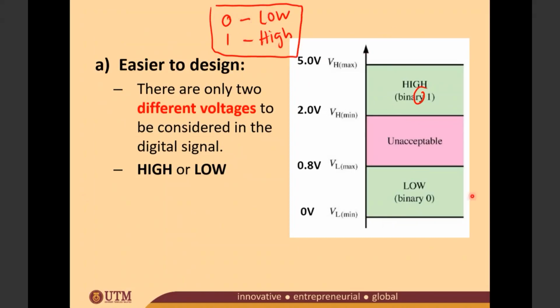Okay, for example, we have the analog signal that we measure. For example, we take a temperature. So any value. Okay, so the maximum value here, if you look here, is the voltage that is coming from your sensors, your thermometer sensors. For example here, the minimum value is 0 volt and the maximum value is 5 volt.